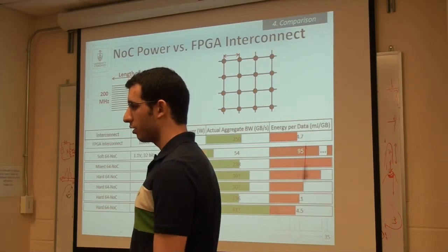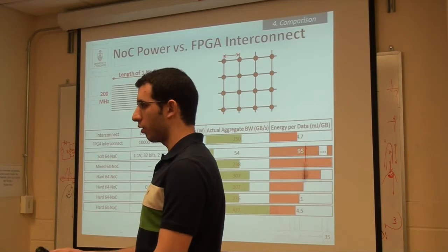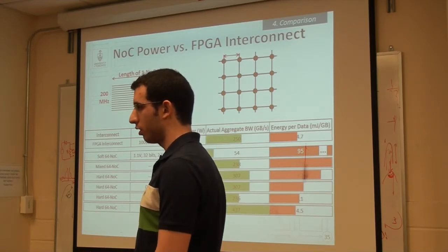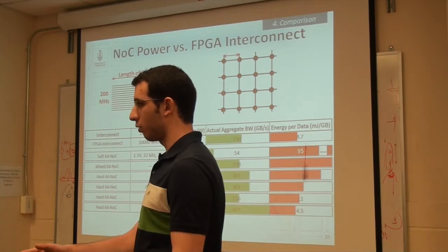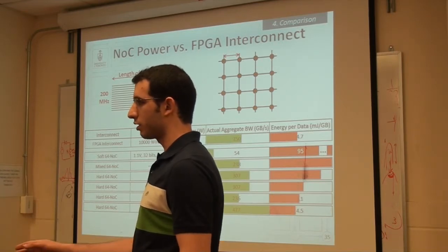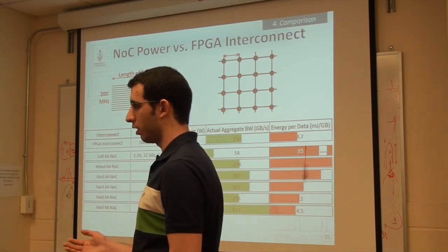I get it a lot. So first of all, you can sort of get around this by assigning traffic priorities, right? You can say I have some latency tolerant transfers here. They will get traffic priority equal 1. They have their own virtual channel. Nothing else can stop them. And then you can sort of estimate an upper bound on the latency that they have through the NOC.